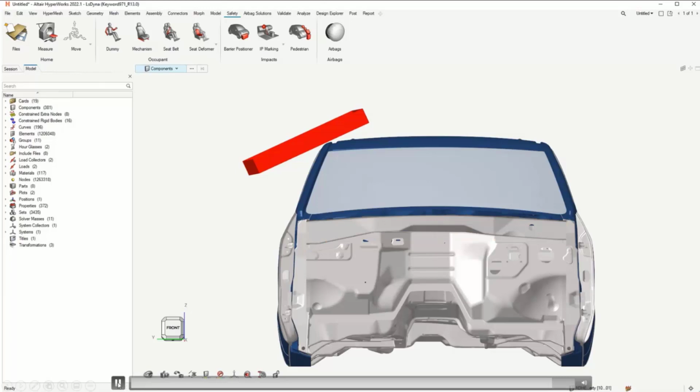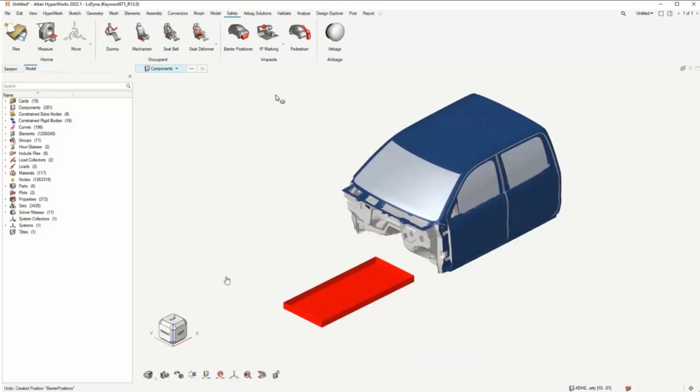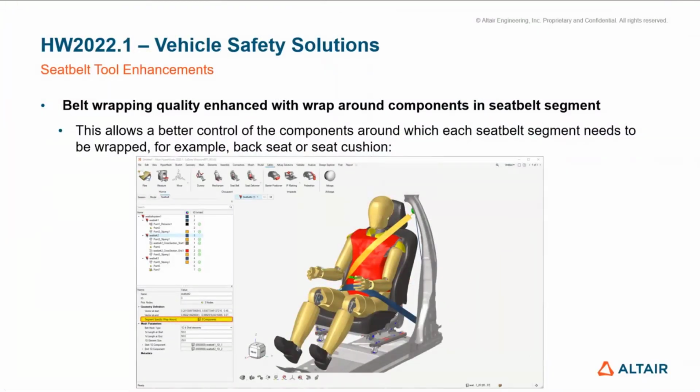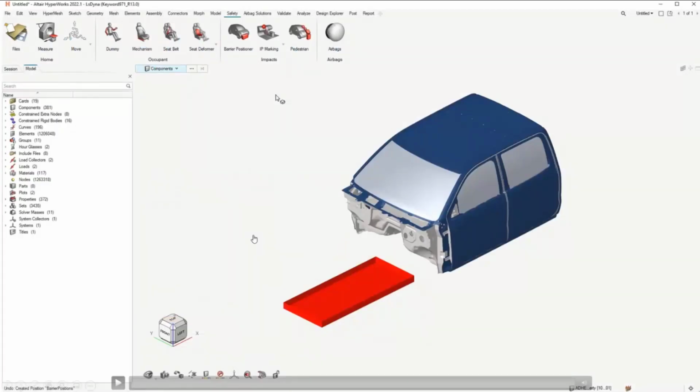As a comment on this process, again, just to recall, within this process we are only positioning the impactor. We are not generating any loads or boundary conditions. So we are not setting up the complete load case within this process, but we consider that the plate, for example, can already have the imposed displacement or the displacement load already defined. So pretty much once you have positioned the plate, the load case is more or less already set up.